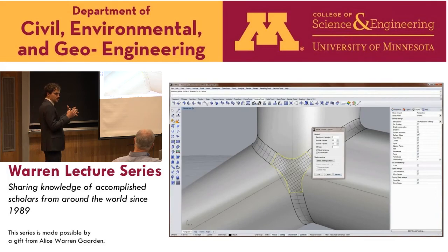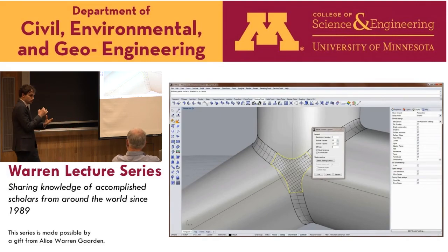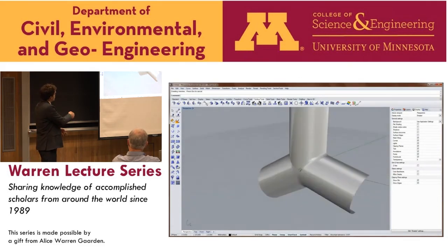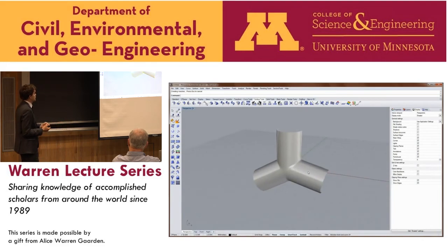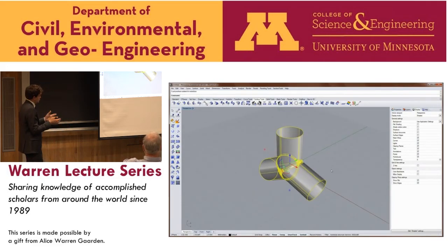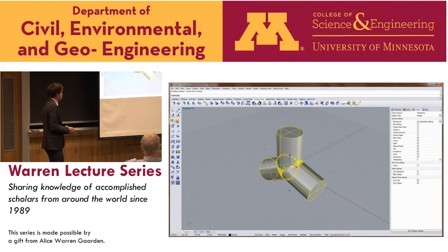But the problem here with trimming surfaces that are connected along trimming lines is that they're not fitted. So you see here, this is the parameterization of this inner trimming surface. You see that the parameter lines along these trimming lines lead to cut elements in the parametric domain. So from a visualization standpoint, everything is very smooth and looks very nice. But from a parameterization standpoint, we have several challenges. One is we have to deal with cut elements. And the second challenge is we have to make sure that our physics here, the shell physics, are correctly transferred between surfaces across unfitted trimming curves.